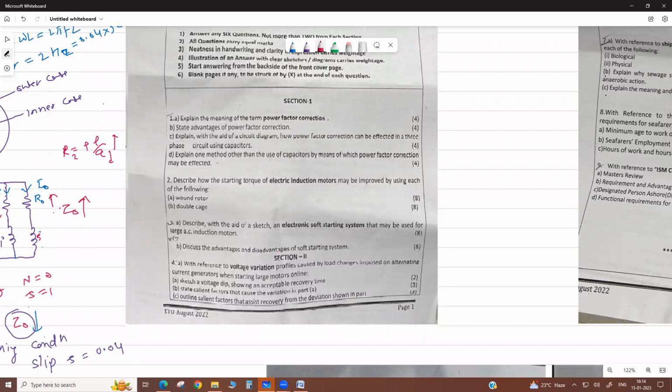Even if you do automatic star delta starter also, there is a contact moving time. During that period, the motor does not get a voltage. Due to inertia, it rotates, but the voltage is gone. It is cut off, then it is multiplied by √3 times.